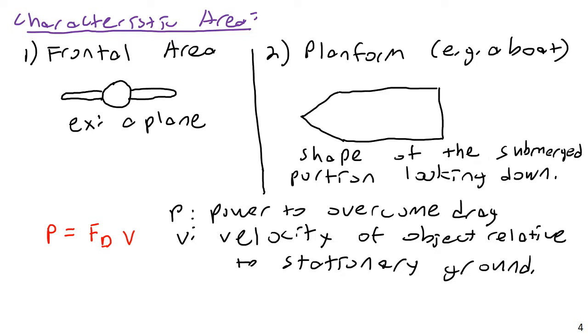So if you have a plane in a wind tunnel, it doesn't move. It isn't doing any work, but to actually do work, you need power to overcome that force. Okay, and to get the drag coefficients, as I mentioned, for very basic shapes you can find formulas or just values for many common shapes, and you can find many of these in chapter 9 of the Munson text.